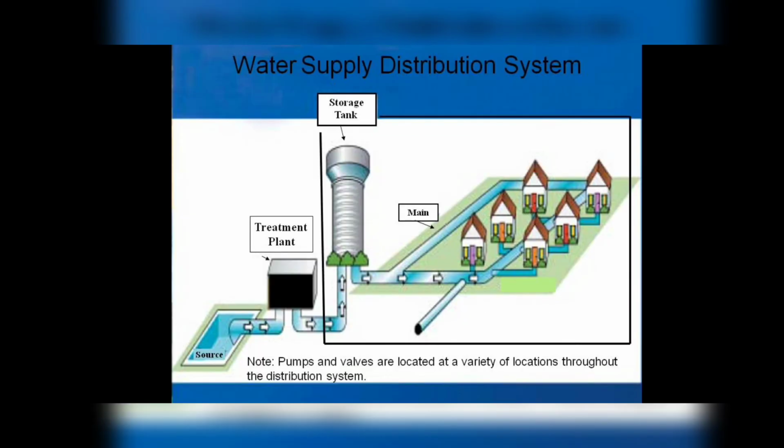Distribution. So, how does the water come out of your kitchen tap? The stored water is pushed through underground pipelines all over town in what is called a distribution system. The distribution system consists of large water pumps at the treatment plant, overhead water storage tanks, large pipelines, smaller pipelines, fire hydrants, valves and water meters in your front yard.